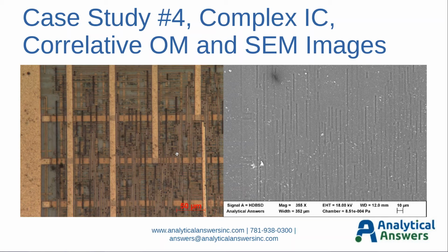And again, the correlative optical and SEM images show different contrast mediums of the same sample. We can see color and we can see circuitry below the passivation here, whereas in the SEM image we can just see the passivation layer. If there were a defect here, it might show up as this kind of dark region right here if it were an ESD or electrostatic discharge defect.